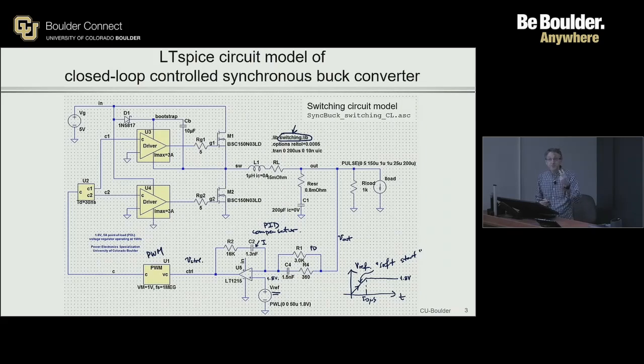That pulse width modulator has parameters. The key parameters being the switching frequency, which in this case here is 1 megahertz, and the other parameter being the VM, right? VM is the amplitude of the sawtooth ramp. You can go inside the switching.lib library and look at the netlist for that sub-circuit that implements the PWM function and see the details of how that actually is implemented. Then the output signal right here is going to be a pulsating logic level control waveform with a duty cycle D being proportional to the control voltage at the input of the pulse width modulator. Okay, we understand that.